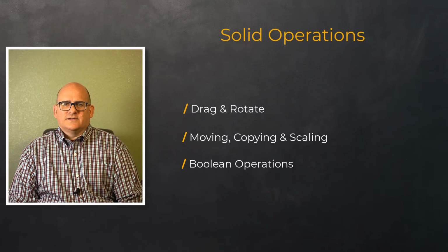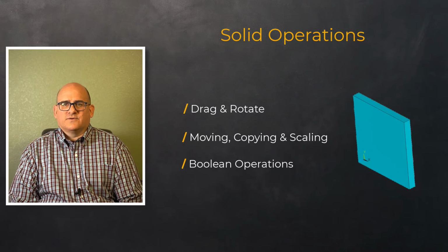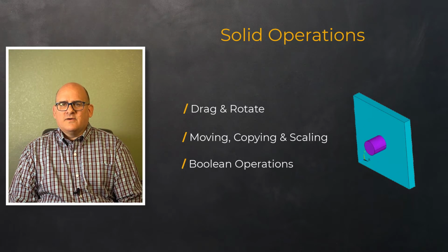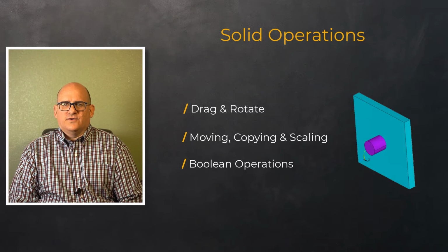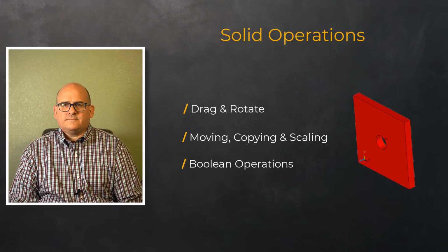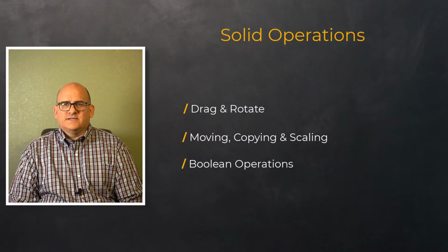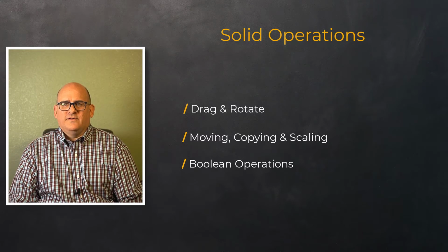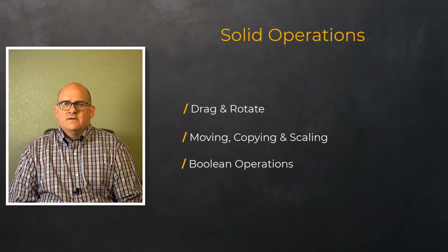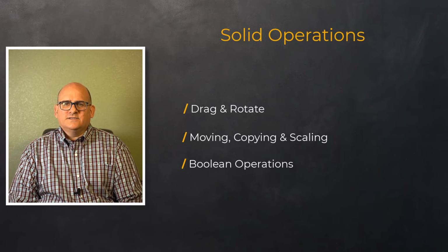These operations can be done on solids created by both top-down and bottom-up approaches. For instance, if we wish to create a hole in a part that is created by a bottom-up approach, we can create a cylinder as a primitive in the location of the hole and use the subtract Boolean to cut out the hole from the part. Often, Boolean operations are used in tandem with copying and moving operations in creating complex geometries and assemblies. While this is not the entirety, the discussion so far provides a good overview of solid modeling in mechanical APDL.